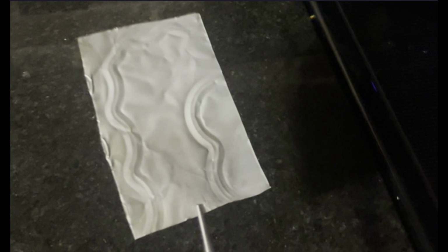When looking at the metal sheet, it's clear that it isn't smooth. It has some ridges and etches in the surface, which increase its surface area. An increased surface area decreases the convection coefficient, and this was not taken into account. Additionally, during the experiment, heat is being transferred away from the sheet via conduction from the metal probe and the metal forceps, so the change in temperature is greater, so the apparent convection transfer is higher than what it actually is. However, the surface area over which this occurs is very small because the area where these two metal objects are touching the sheet is small. Therefore, the effect on the convection coefficient is negligible.